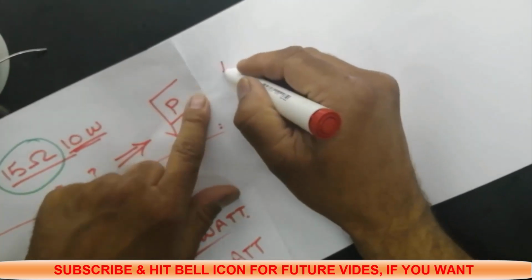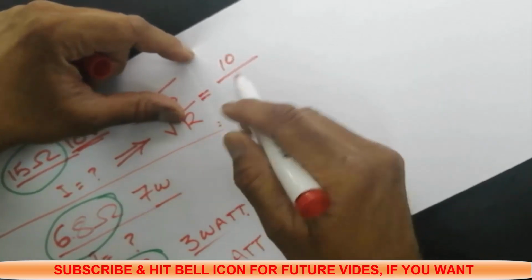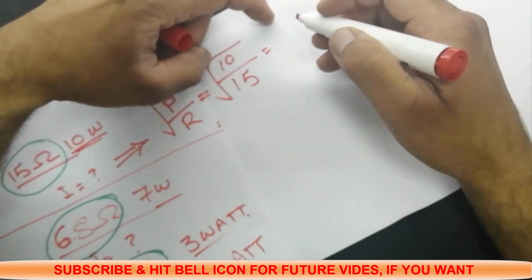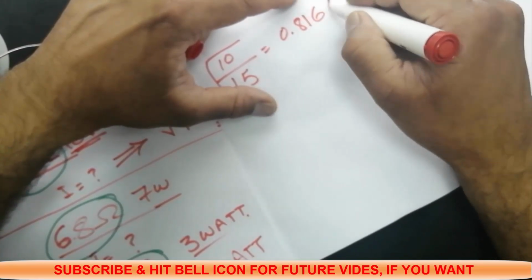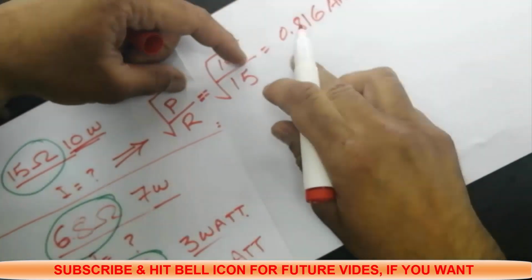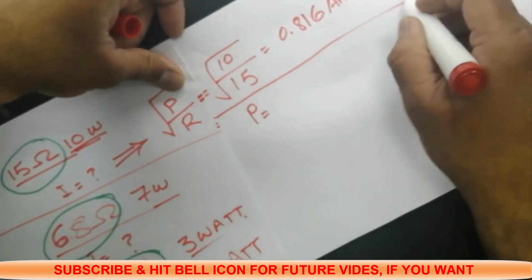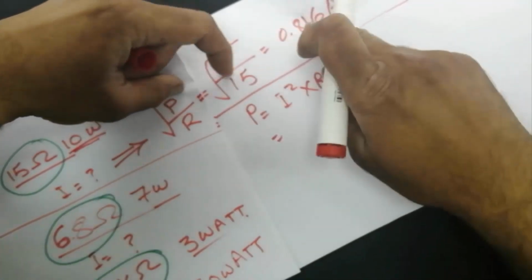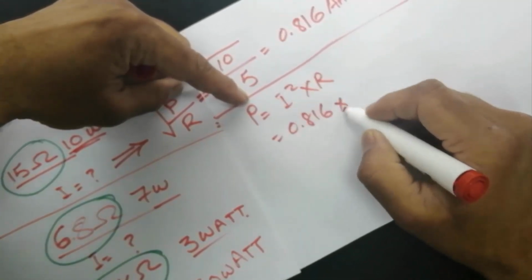And now we will discuss how to select a resistor. If we have a circuit, we have to select a resistor value. First, I will go in reverse. I have 10 watt, 15 ohm. When I calculate it, it is 816 milliampere. Okay. P is equal to I squared R. I will cross verify. I is the amount of current.